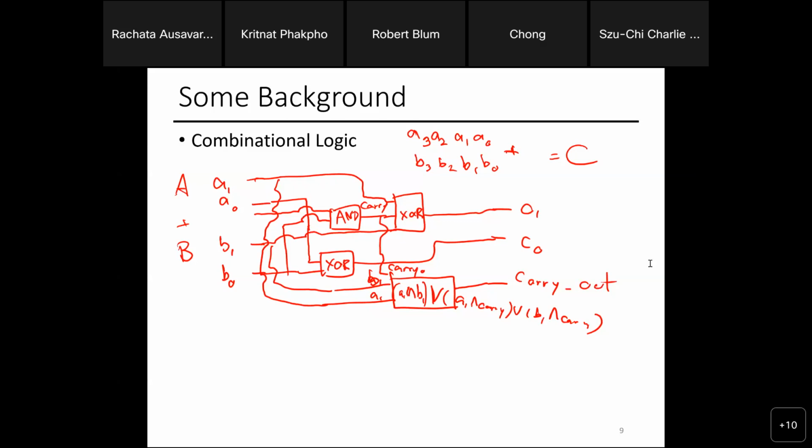So you can imagine this is gonna look quite slow if you have to add, for example, 64 bits, right? Why? What becomes my critical path? Whatever carry I have to do, because the 64th bit carry is depending on the 63rd bit, which depends on the 62nd bit, which depends on, like induction, the 0 bit. That's going to be my critical path, right? So as I said, this is not the optimized design in the real CPU.